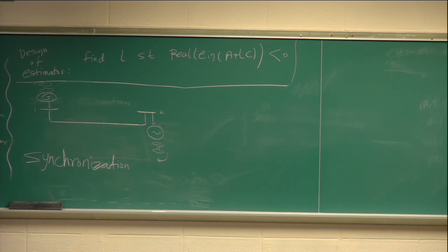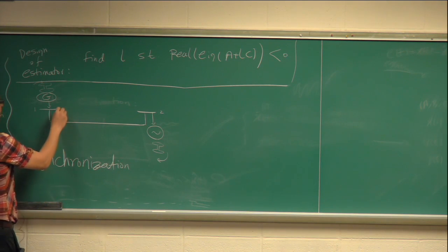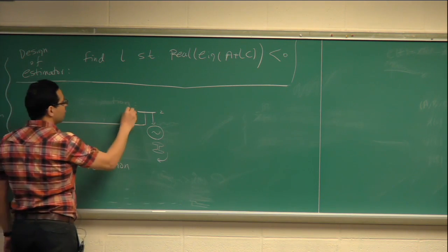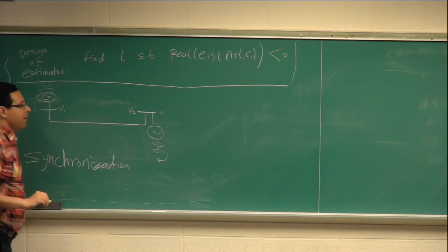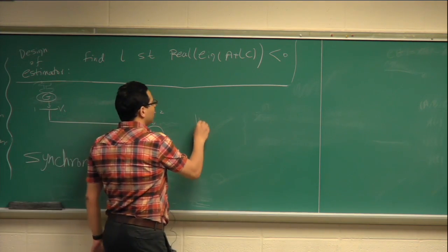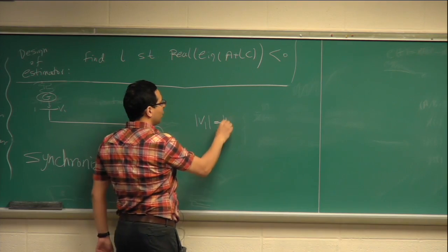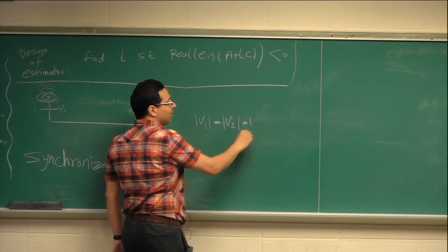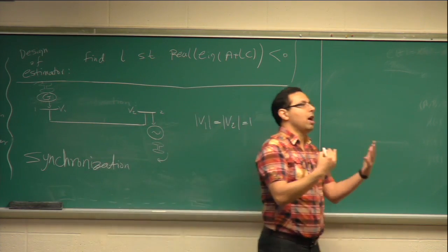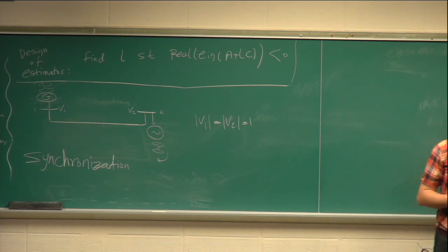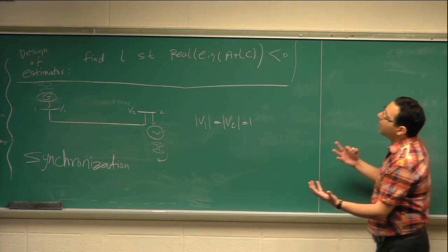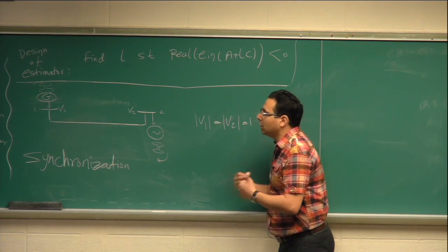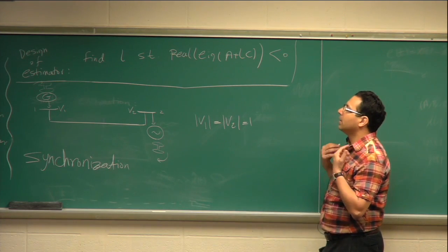The first thing, if you remember, a while ago we talked about, probably in lecture 2 or 3, was that there is a voltage here, a complex voltage. In practice, we want to make sure that voltage magnitudes are close to their per unit value. Voltages are close to 120 volts, because that's how we design the system to make it efficient, to detect faults, and to make the system operational.